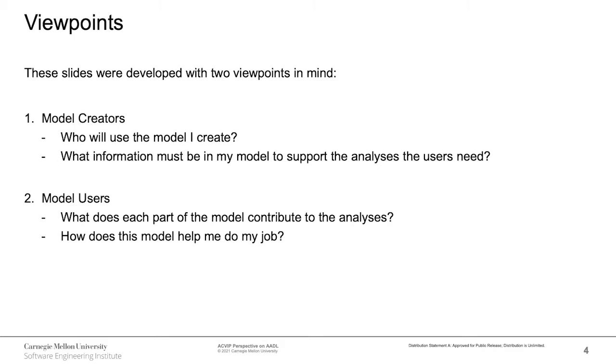Model creators are responsible for providing a sufficient amount of information to describe the proposed system and support further AADL analysis. Model creators will specify data processing and transmission, communication transfer mechanisms, as well as system architecture to outline how the data is handled. When the model is ready, model users can review analysis provided by AADL to check for errors and inconsistencies in current design, and to verify that the current model meets the requirements and produces sufficient results.